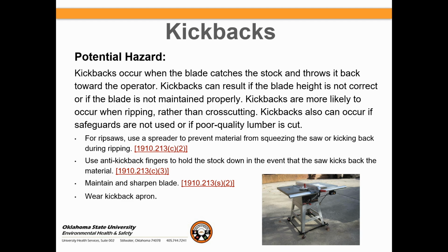Use a spreader to prevent material from squeezing and kicking back during ripping. Use anti-kickback fingers to hold the stock in the event that the material starts backing out. Maintain sharpened blades. Another thing too is wear a kickback apron if you have such available.